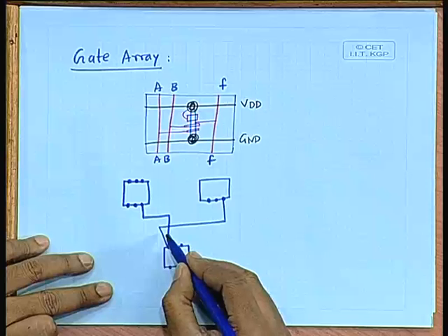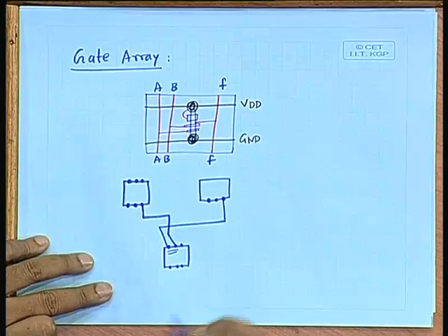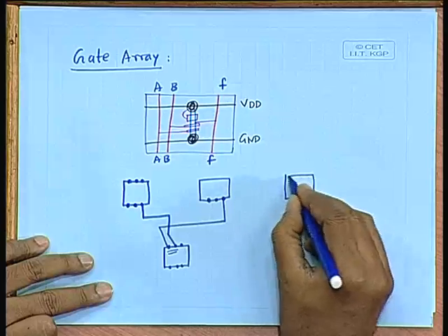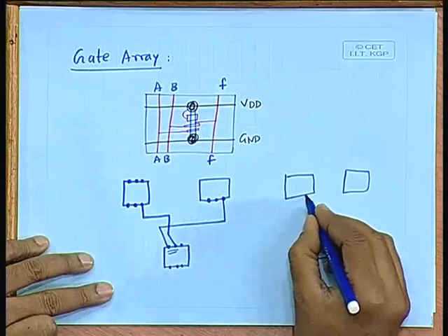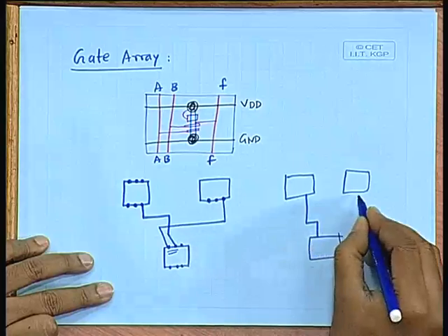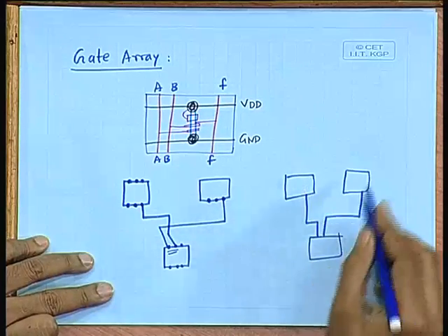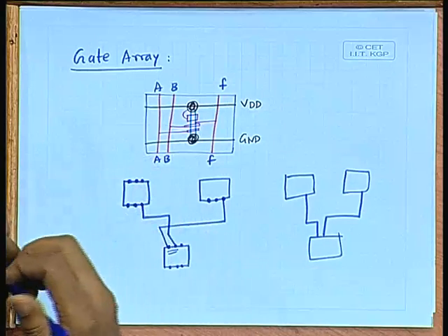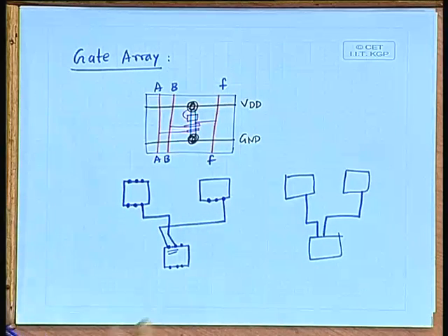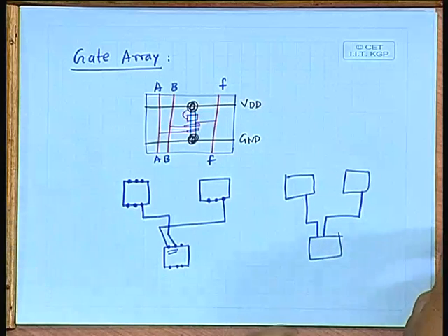Obviously, here is a crossing, but if you swap these 2 pins, then you can get another solution where there is no crossing. It becomes like this. This output will come to the first pin, this output will come to the second pin. So, the routability is improved and the congestion is less. That is how equipotential and functional equivalent pins are utilized in routing and congestion control. Okay.